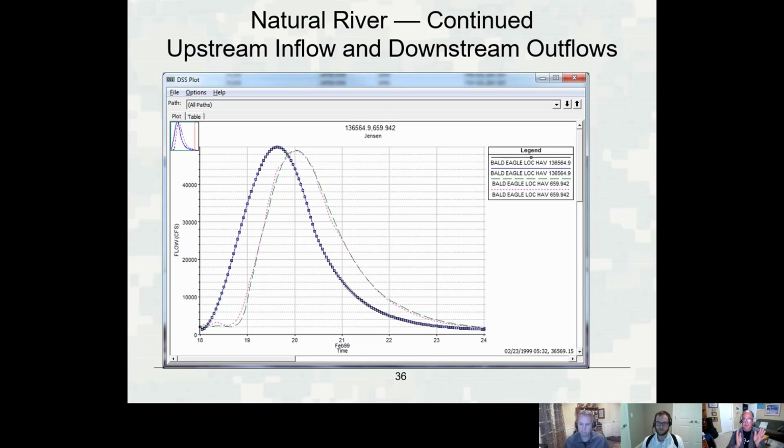So in reality, there's some limit. Yes, you want to have smaller cells to capture the change in water surface, but if you make the cross sections too close together, the finite volume method is where we're actually going to have trouble with stability, because the cell's too small, and that will dictate using a much smaller time step to get it to solve accurately. So the Courant condition is more important for the finite volume. Right, because it's kind of like a fill and release type of thing. How much water does it take to fill it over the time step and go out?